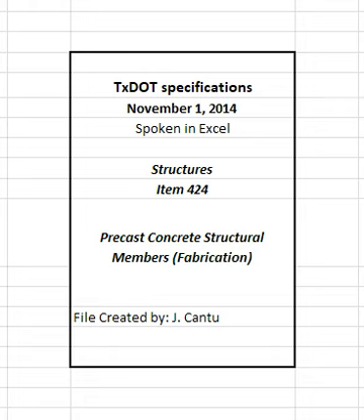After application of final load, measurements on individual draped strands to establish differential stresses at selected points on the member will be averaged at a cross-section of the member, and the averages must be within 5% of the theoretical elongation. The measured elongation of any individual draped strand must not vary from the theoretical elongation by more than 10% at any measured cross-section. Suspend tensioning operations until the problem has been identified and corrected in the event of discrepancies greater than these tolerances. Other methods to measure the intermediate load and final load in the draped strands may be submitted for approval.